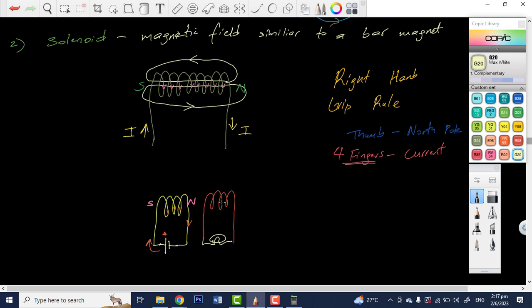However, if we want something meaningful, we simply replace this DC power with an AC power, and we're going to have that continual change in magnetic field, which will continue to induce a current in the secondary coil, which will give us current continually flowing in this light bulb. So that is the basic idea of a transformer. That's really what's going to happen right here. So that's that.